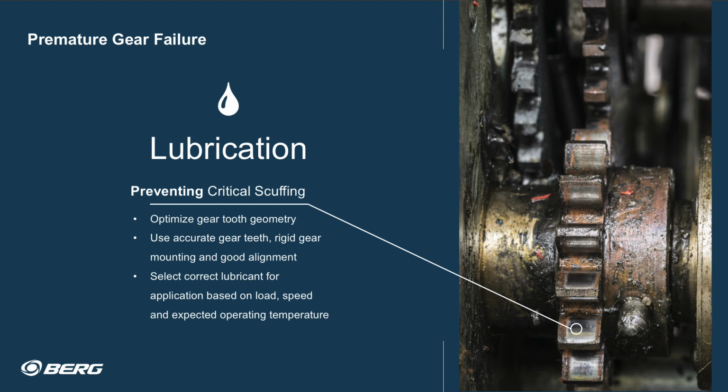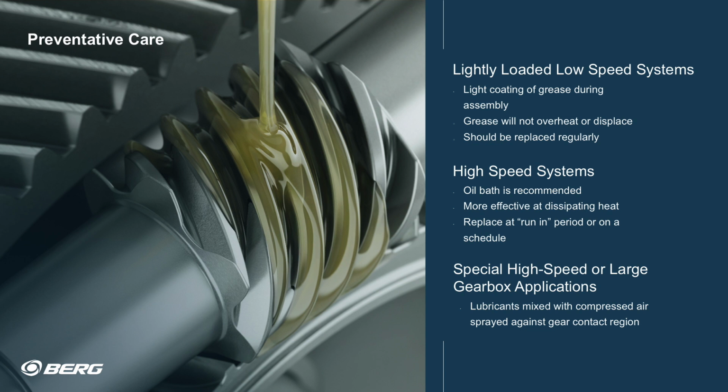There are many good resources for selecting lubricant, both on the internet and with your local lubricant distributor. Please leverage these resources to ensure you use the appropriate lubricant. Once the lubricant is chosen, the designer must decide how to ensure that it is present on the gear faces when contact is made.